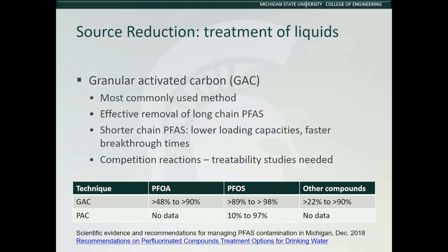One of the major challenges of granular activated carbon and also powdered activated carbon is the fact that other organics and even some of the metals will sorb onto the surface of the activated carbon and compete for surface sites. And many of these compounds are found in much higher concentrations than are the PFAS.